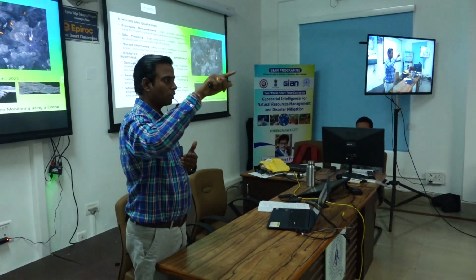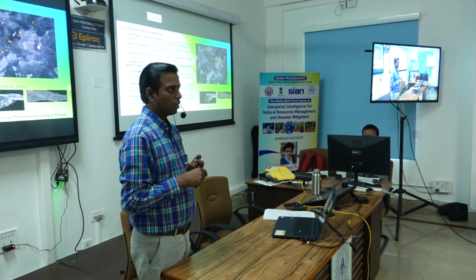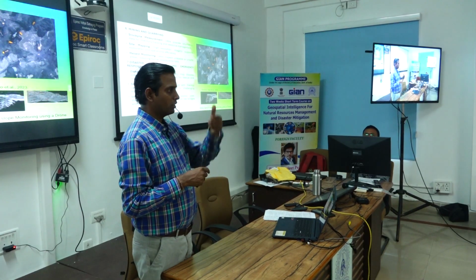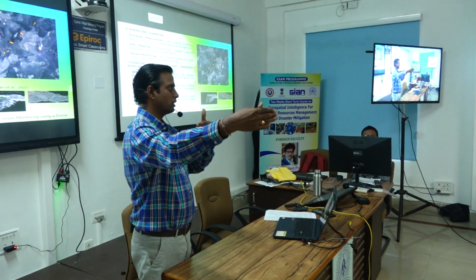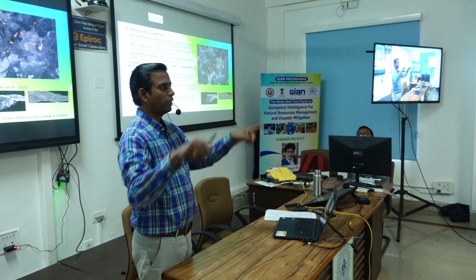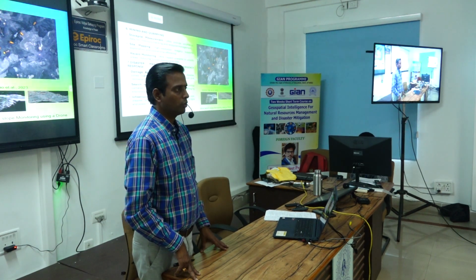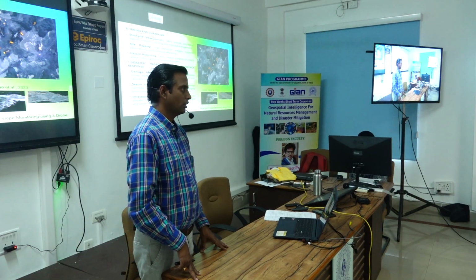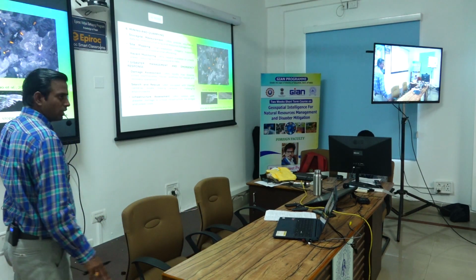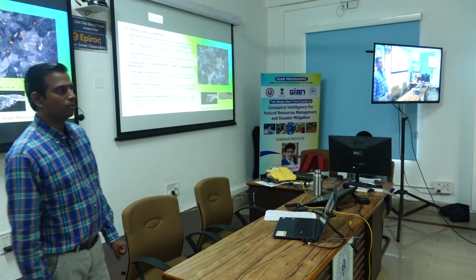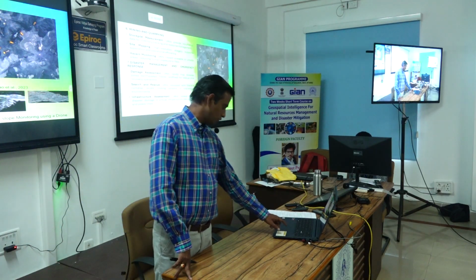I said that we will get the point cloud data, x comma y comma z. Now what is z today, and what is z after 2 days? The difference of these, multiplied with the area, gives you the volume of the ore which is extracted. Okay? Now these are some of the figures which give you an idea about how we can utilize the UAV.